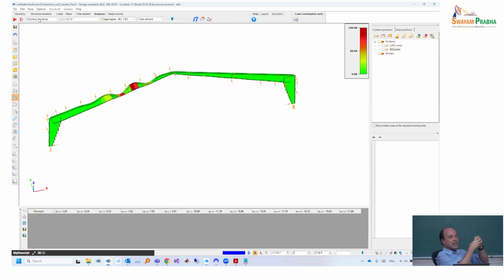What is important is the distribution of this energy over the structure. Where there is a high concentration of this energy, those are probably the relevant parts, and where the energy from this given mode is very little, those parts are probably not relevant.